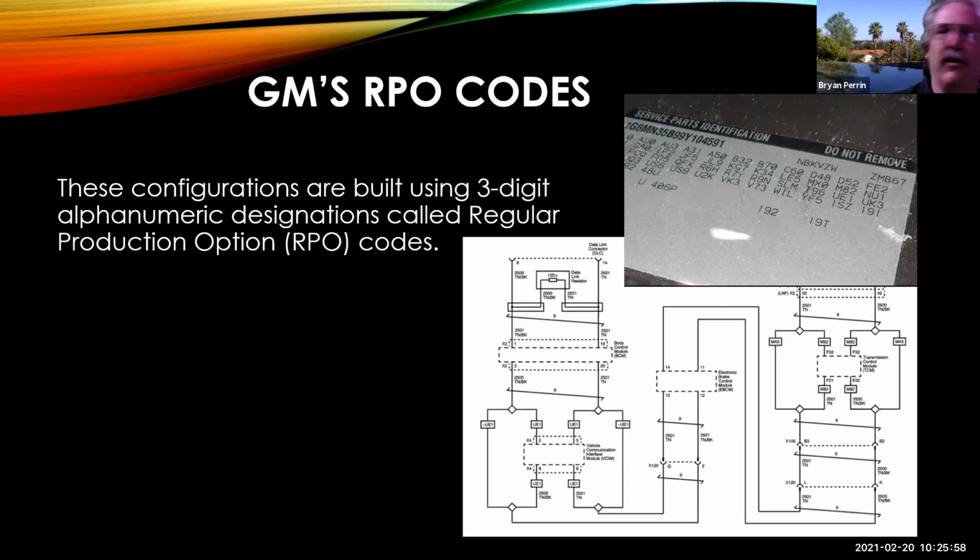Yeah. So we go to this backup programming where I don't need to know how fast I'm going. I don't need to know this. I don't need to know that. I can still make the engine run. We're just going to run off our load sensor and make the best choices we can. And I've got my O2 sensors, and here we go. Understand, maybe we're going to get 20 miles a gallon instead of 25 miles a gallon, whatever. We're still getting there. Okay.